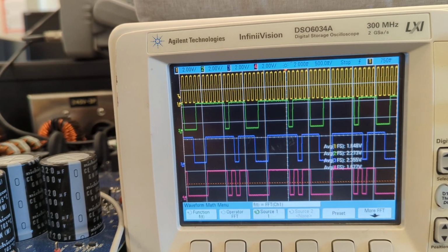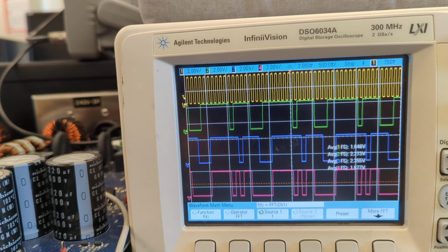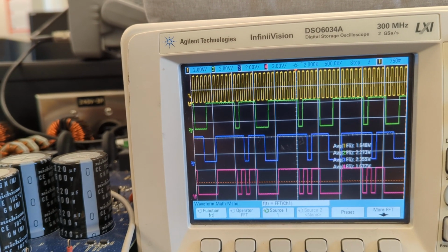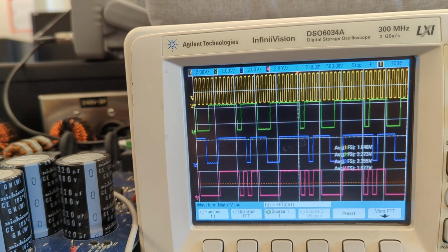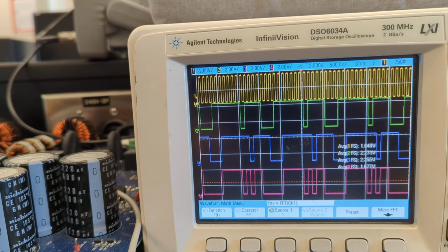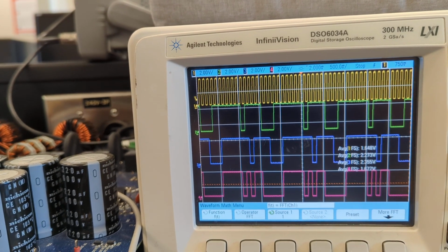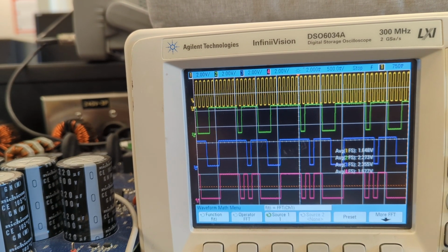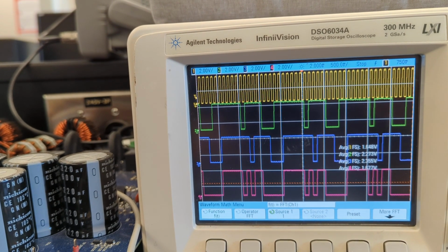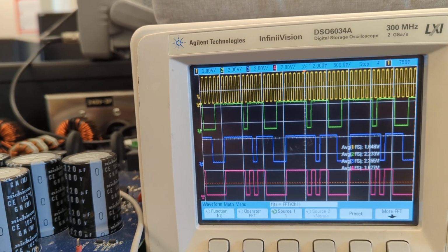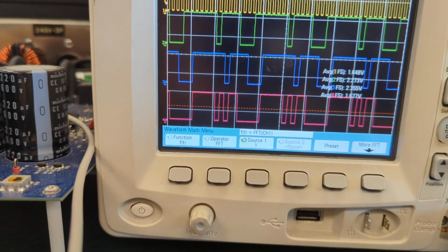And that average is actually how long you're on. So if I was connecting these signals to an LED, the green and the blue signals would be on 3/4 of the time, and so they would be brighter than the purple signal, which is on 9/16 of the time. And this can actually be used to drive things like power LEDs and motors to get rid of the higher harmonics.